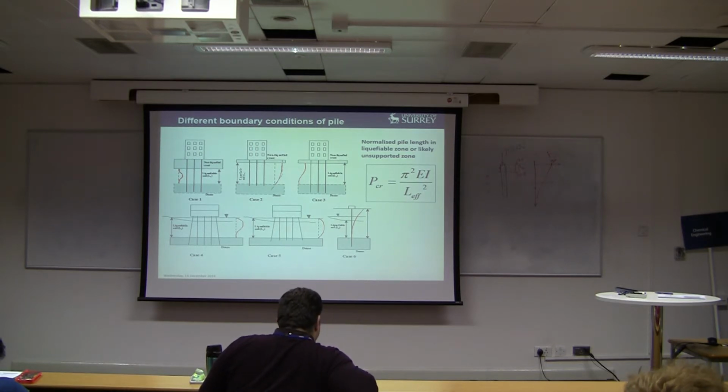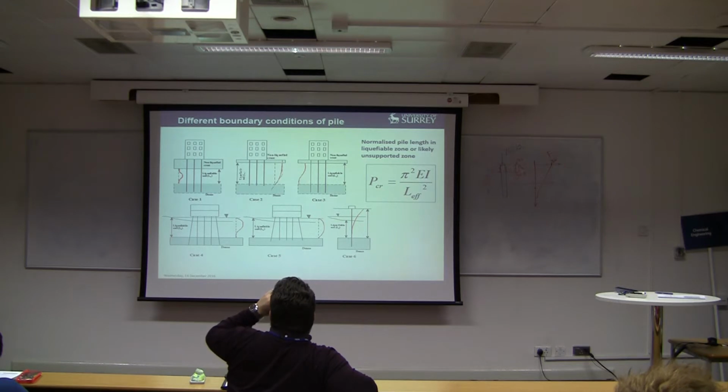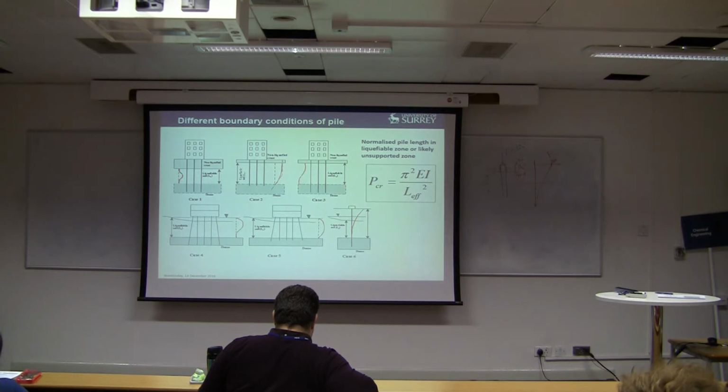But by adding this, aren't you making the foundations astronomically huge? If you look into which buildings survive the earthquakes, you see what the piles are. Instead of many small diameter piles, you need one large diameter pile. Is that why they do performance-based design, because sometimes they can't afford that cost? So you don't go for many small diameter piles, you go for one large diameter.